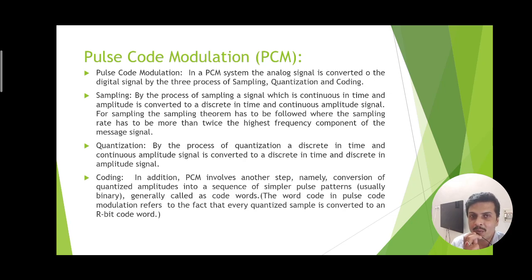So how is it done? The pulse magnitudes are converted into a fixed set of values by the quantization process, therefore the quantized signal is itself a digital signal, because it has a finite set of magnitude values only. These finite magnitudes are further encoded by binary encoding, in which 2-bit, 3-bit or 8-bit codes may be used for encoding each of the pulse magnitudes.